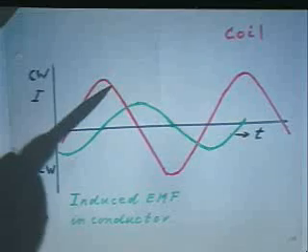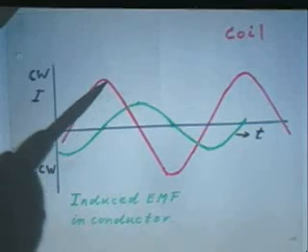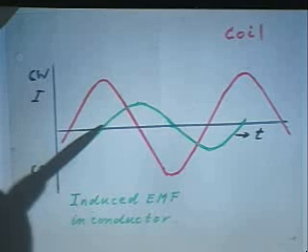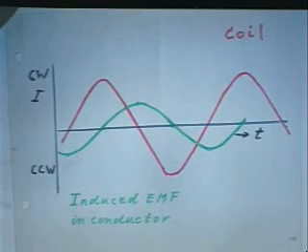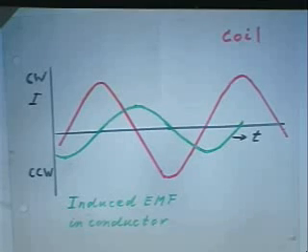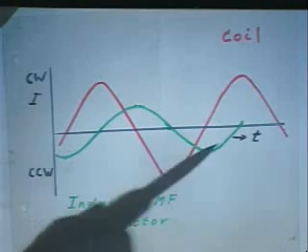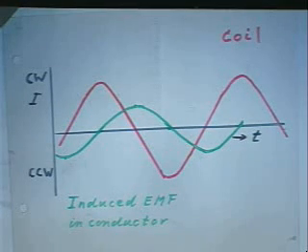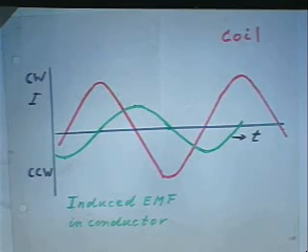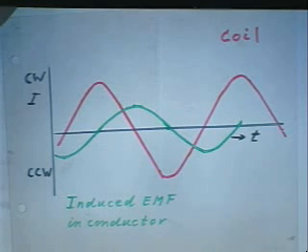But now when the magnetic field goes down, when the current in the coil goes down, immediately the EMF flips over, which is what I just mentioned to you. And therefore, if the induced current and the induced EMF were in phase with each other, half the time you would have attraction, and half the time you would have that the two repel each other. And that won't give you magnetic levitation.